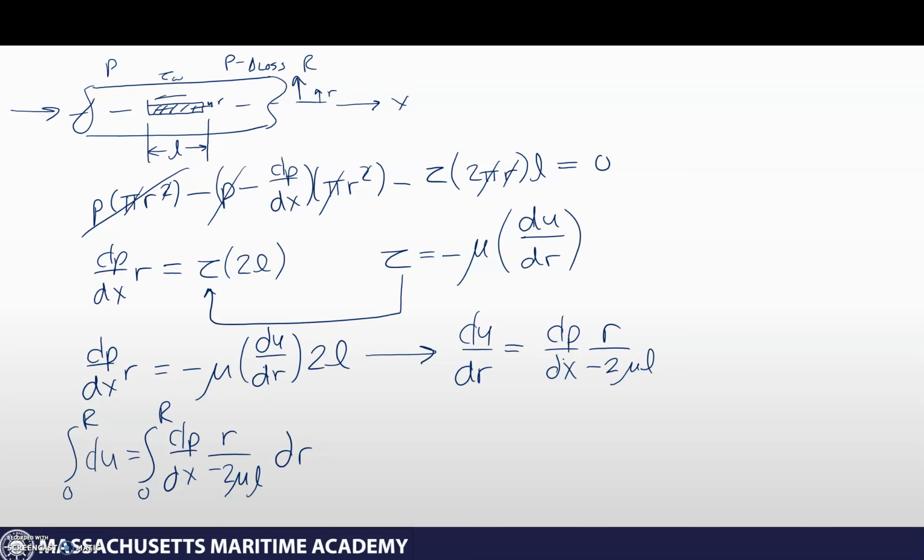We have the no slip condition, so that tells us that at u of R, my velocity will be 0. That is because the fluid that's next to a solid object will maintain the same speed as the solid object, because there's no slip between the fluid and the solid object. Since the outside of the pipe is not moving, we'll have things set at 0. When we plug that in, we only need one boundary condition because we're only integrating one order of magnitude.